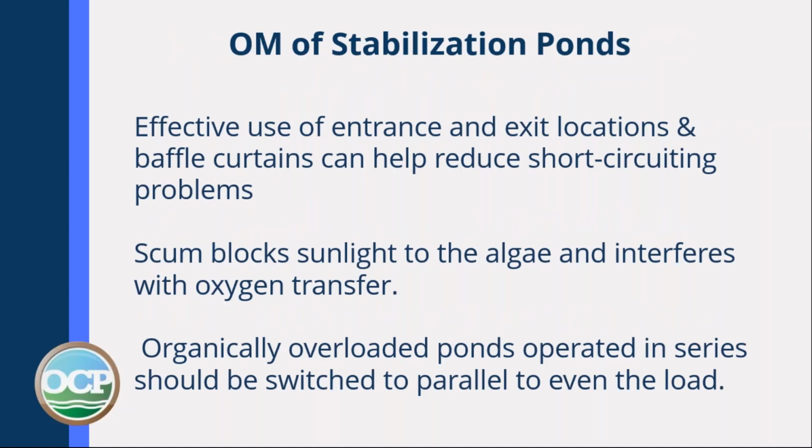You must have effective use of entrance and exit locations and baffle curtains to help reduce short-circuiting problems in your ponds and lagoons. Water will try to find the quickest way out from where it comes in. Scum buildup can block sunlight to the algae and interfere with oxygen transfer. If your ponds become overloaded and they're being operated in series, you should switch them to parallel to spread the load between the 2 ponds.